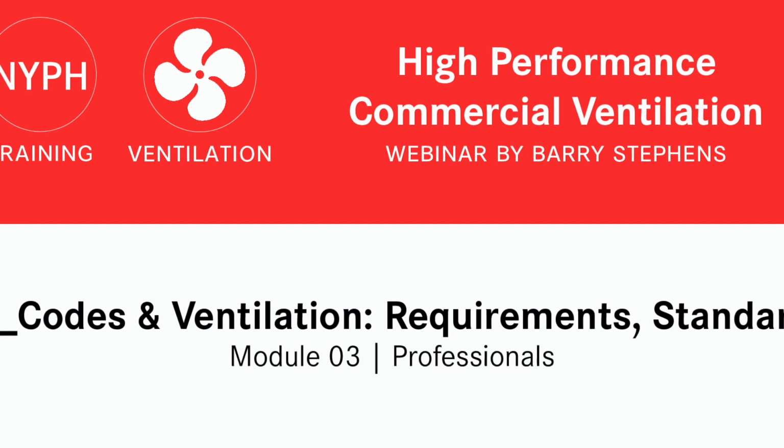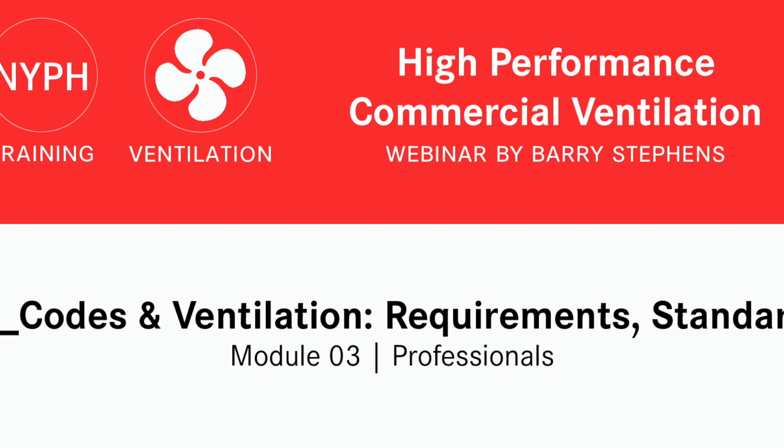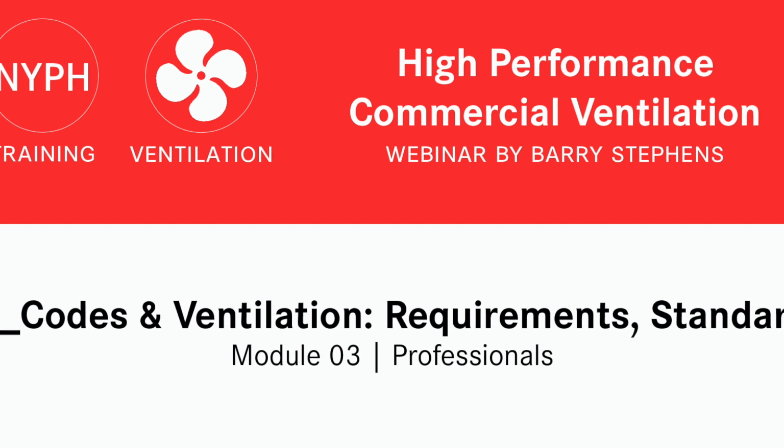Okay. So also, we'd have to check locally, but it always takes them time. The latest version of ASHRAE 62.1 in effect adopted residential ASHRAE 62.2. That means ventilation for kitchens and bathrooms and so forth. You used to be able to have an operable window, and that meant your ventilation rate for multifamily in 62.1. That is not going to be that way anymore. But when they adopt that new ASHRAE, every 3 years, ASHRAE redoes the standard.